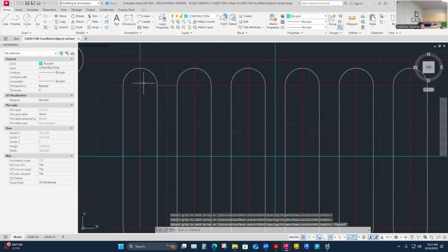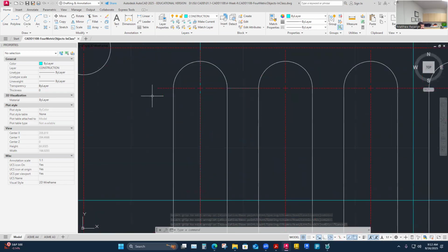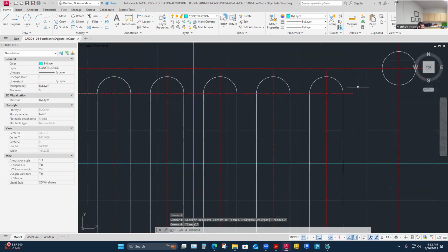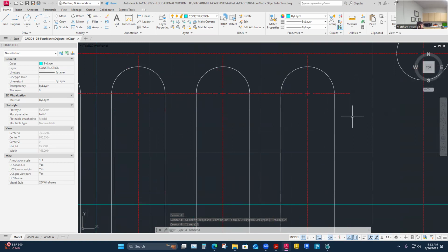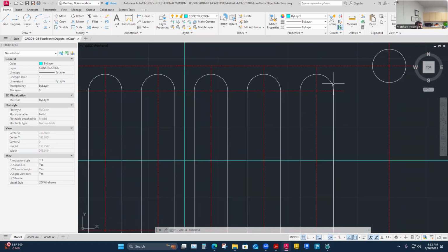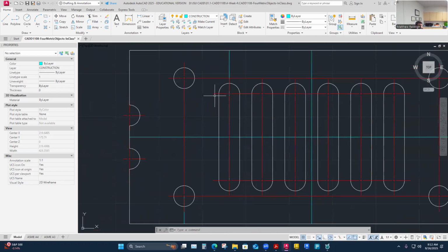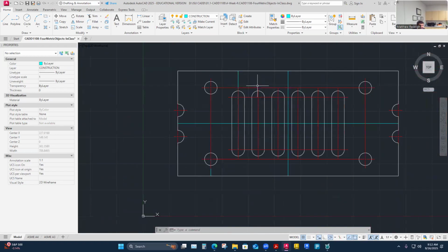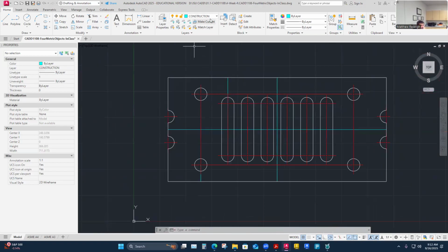It's good to question even the stuff. So now I do have that overlap going on there. I don't know if I still get the control over doing that. I think I would leave that. It's 1 millimeter longer. I think I can break that rule. You break that centerline rule sometimes, and I think that's fine, especially where it's symmetrical. What I wouldn't want is that I know I'm 7 millimeter here in my array, but I'm going to leave it because it's just 1 millimeter, and it's going to be visually symmetrical. So I like this. And then I get the overlap that we didn't have before. This is good. This is better. That's a good attention to detail that I missed, really.